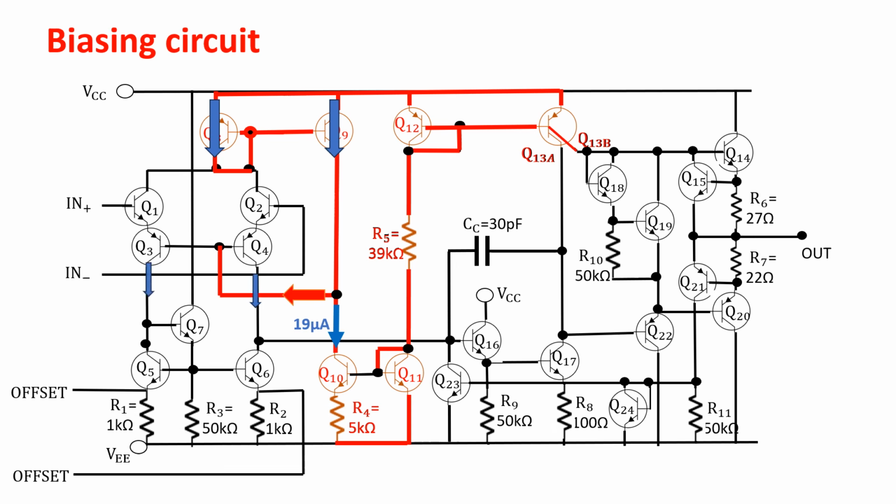Now let's see the function of Q7. This transistor creates, with Q5 and Q6, an improved current mirror. Q7 ensures equal collector voltage for Q5 and Q6, thus balancing the two branches of the current mirror loads. The collector of Q6 is 2 VBE above VE, plus the little drop on R8.